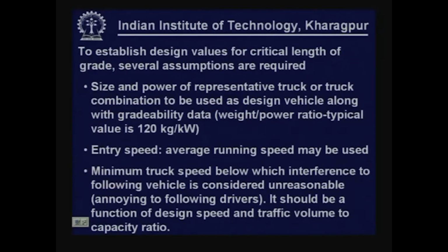Then it is also necessary to define the entry speed, which may be taken as the average running speed on planes. Then the minimum truck speed below which interference to following vehicles is considered unreasonable or annoying to the following driver.